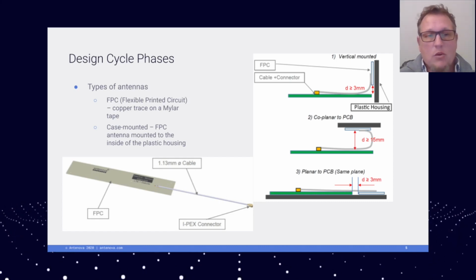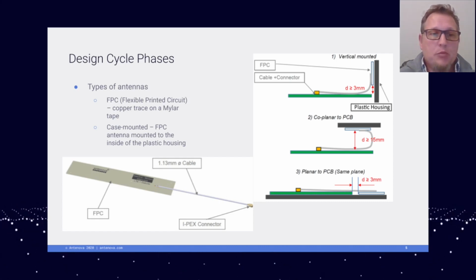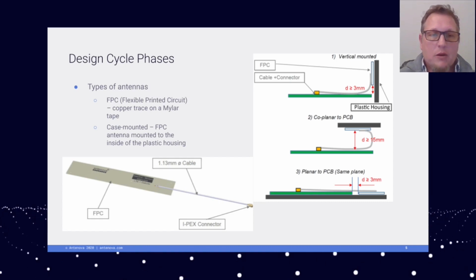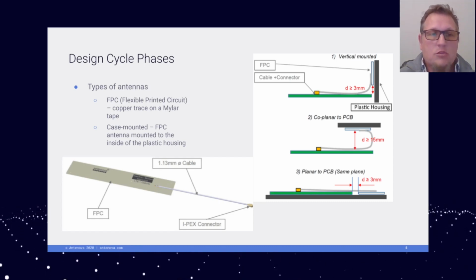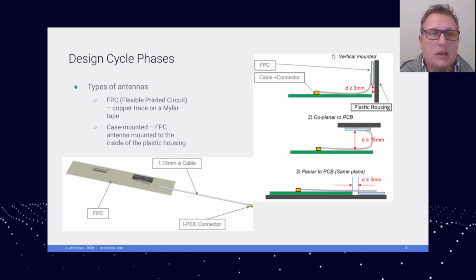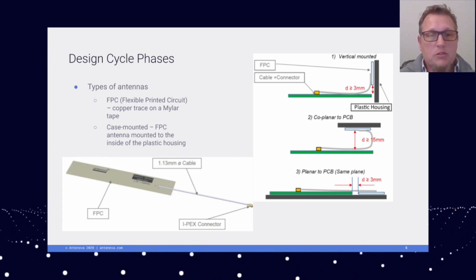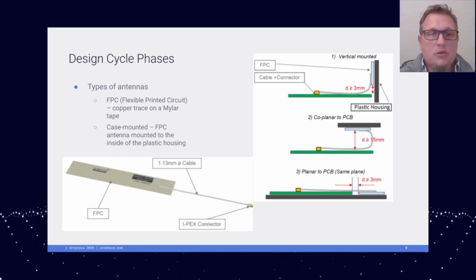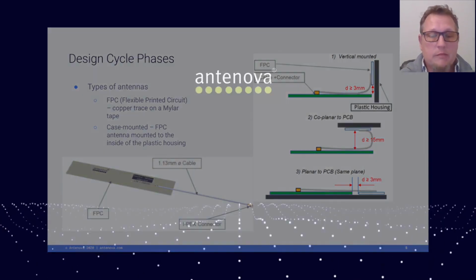One thing you can do to overcome that is to put pins inside your housing or on a carrier so that those pins align with holes on your flexible printed circuit antenna, and you can have a little bit of repeatability.